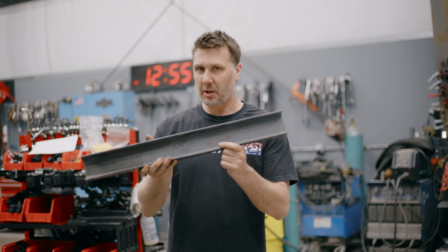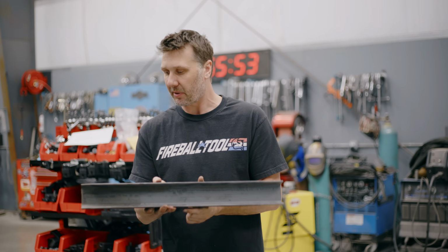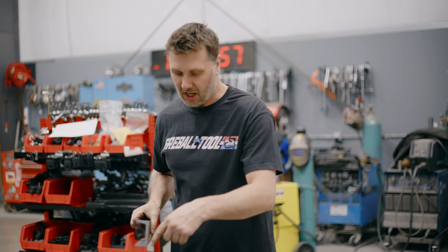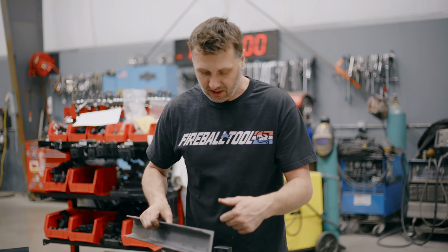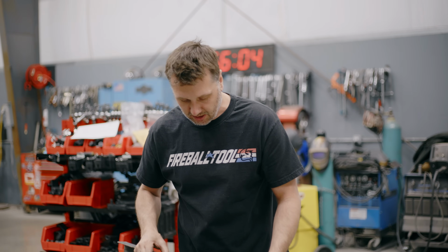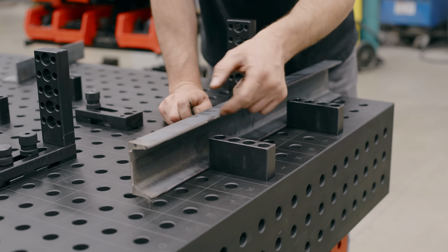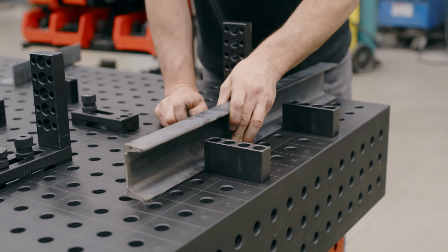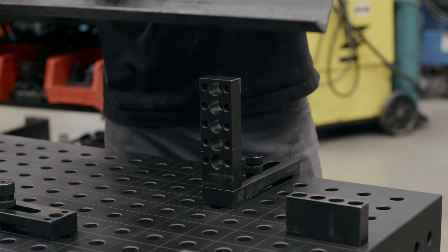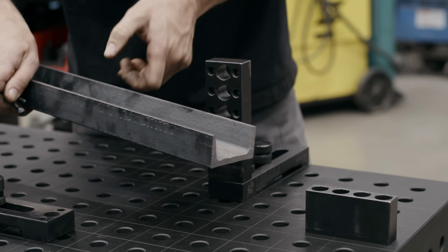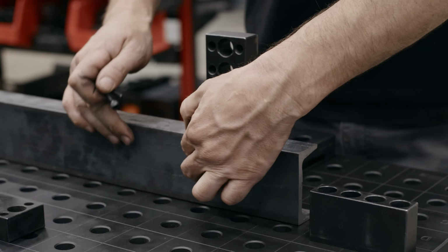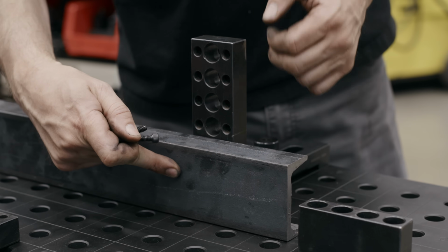For this exercise, we're going to be using small sections of material because I don't really want to waste it, building this just for demonstration, but I would like to talk about some of the things we've talked about in CAD here on the floor. And that was like this 3-inch channel and why I used a 6-inch riser. So we chose not to use a fence block because of this material, right? It can still roll. It's not tall enough. So that's why we picked the risers over here, remember? So now when we have the 2 legs of the angle iron bumped into this, look at that. Now this riser controls the roll of the material.